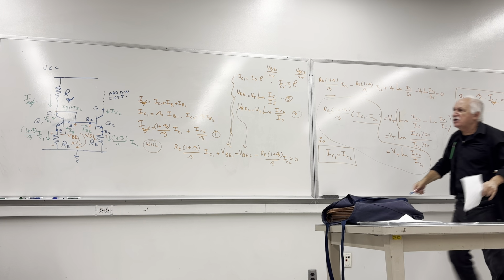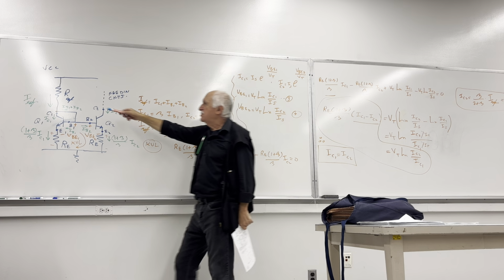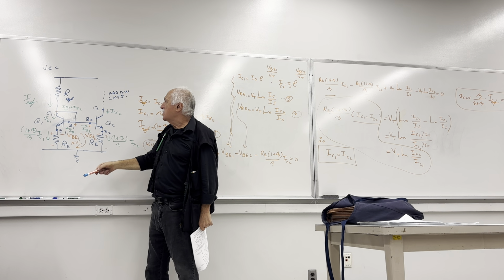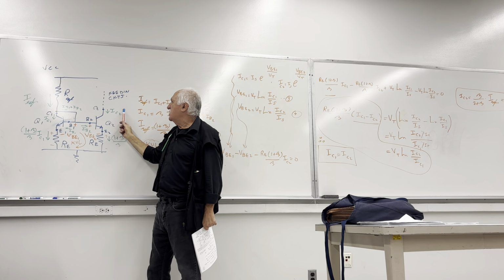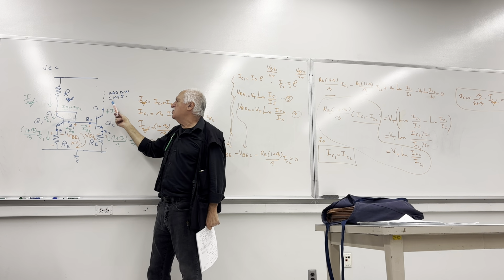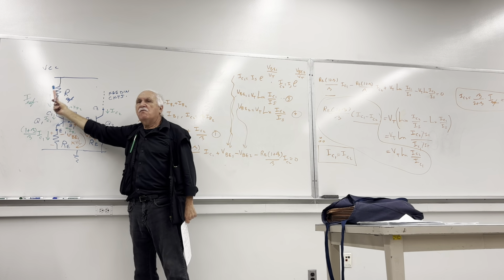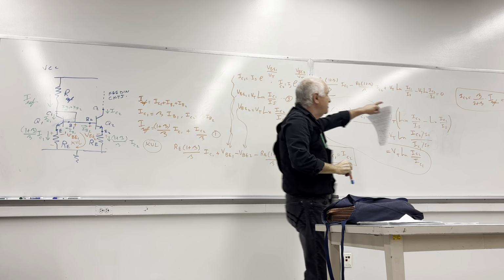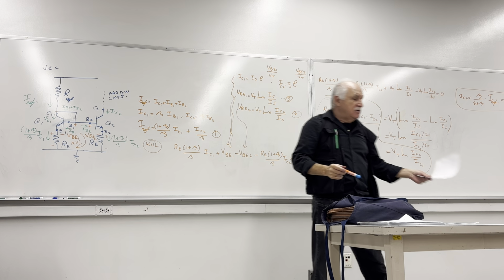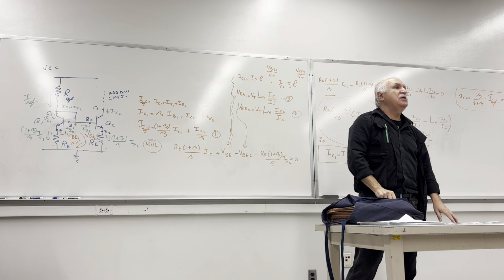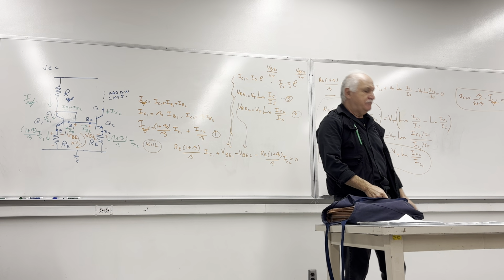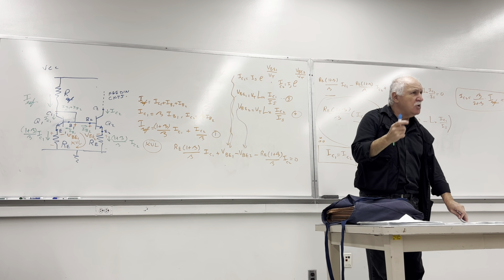That is, we established the current in this resistor, and we got a current in here which is almost a duplicate of the current in the IREF, with a little shortfall because of beta over 2 plus beta. There are current sources even better than that, almost exactly identical, but we won't go there.